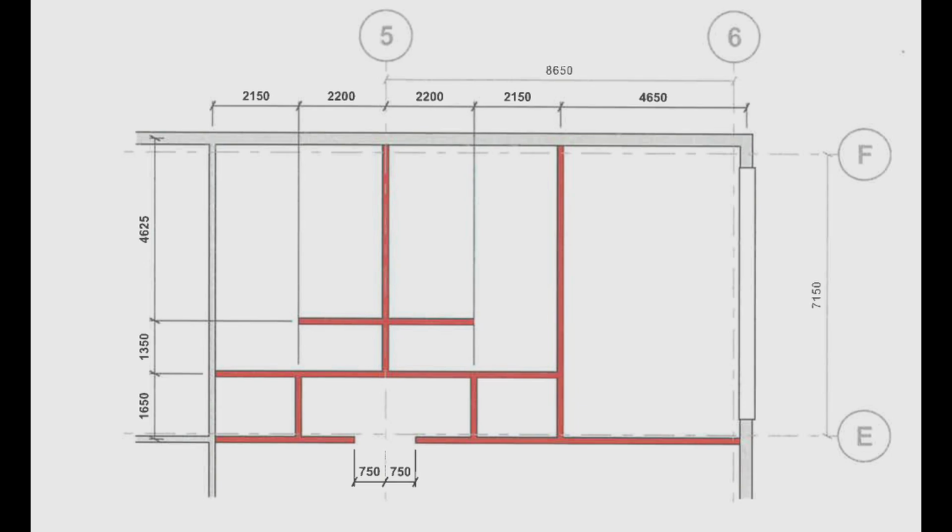This module reinforces the principles we discussed earlier in model development methodology. We start by defining the major building elements: walls, floors, roofs, and ceilings, and we approach them using the same best practice workflow. That means our first step is simplicity. We begin by placing these elements as simplified geometric slabs using a single conceptual material, not complex composite layers. This approach allows us to focus on understanding the functional behavior of the elements, their shapes, their relationships, and how they interact with hosted components.